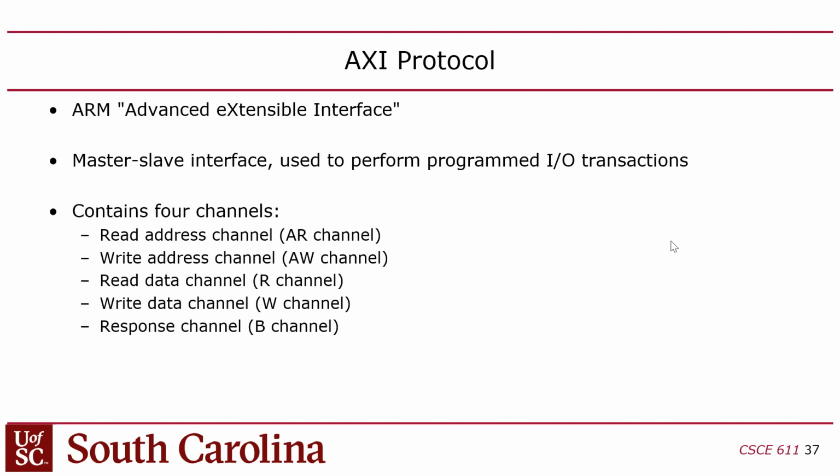So each peripheral has an address range, and if you read or write to the address range corresponding to a peripheral, it goes out on the bus, and then there's auxiliary logic that routes that request to the peripheral. You guys with me? So if you design a peripheral, you have to put this AXI interface on it, right? You have to be able to talk. That's the language, basically, that all these modules speak inside a system on chip.